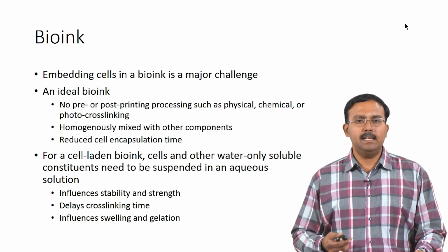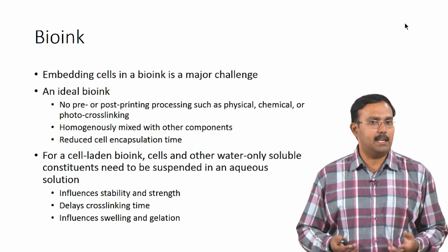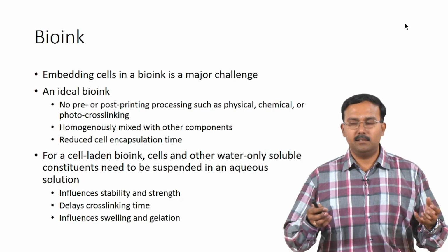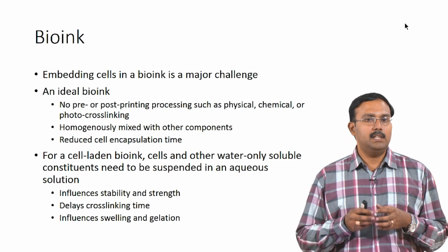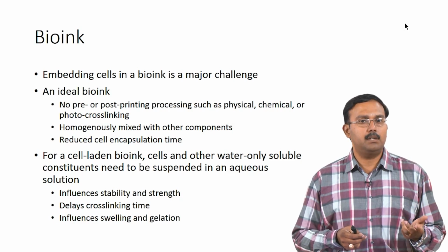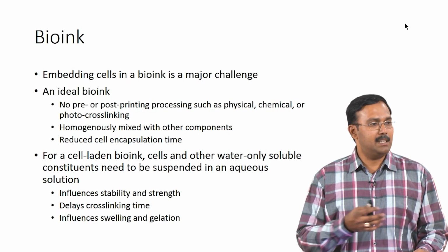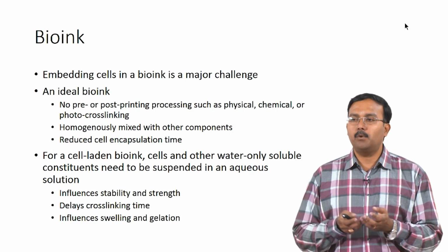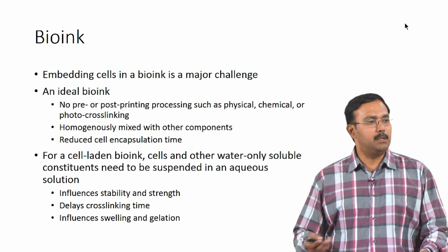For creating a cell laden bio ink, cells and other water soluble components are usually suspended in an aqueous solution, and the concentration in which it is being dispersed and the other components which are loaded can actually have a serious effect on the stability and the strength of the final construct which is printed. It can also delay the cross linking time. It will obviously affect the swelling and gelation properties. So, while you are preparing these inks, preparing the appropriate aqueous media, aqueous solution also plays a role. It is not just about the polymer you use.